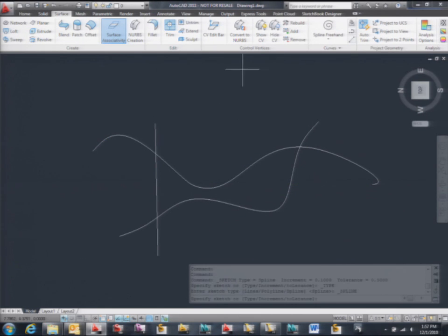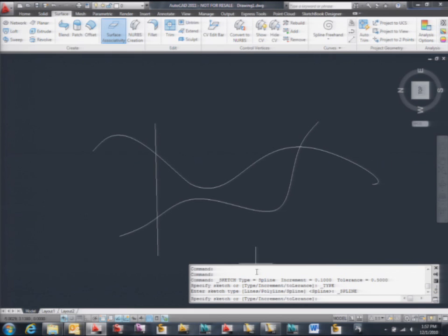This is the whole thing. Spline Freehand is still the same good old sketch command. So if somebody really, really likes sketch, like our friend here, you can still use the points, but maybe now you want to use this thing. So we can do lines, polyline, and spline. We can convert all that into a polyline, a spline, or a line. By default, it's in spline because we assume that this is better for this.